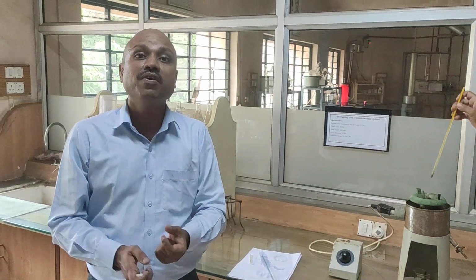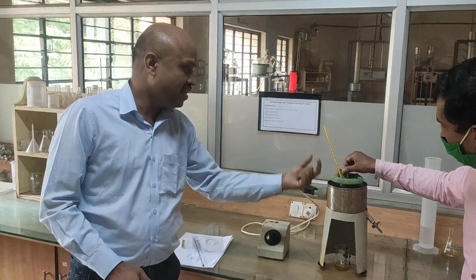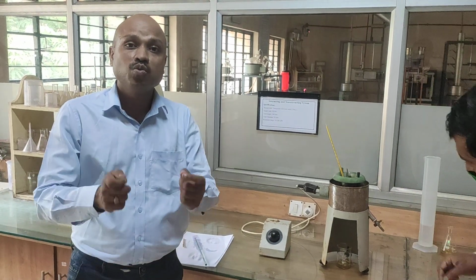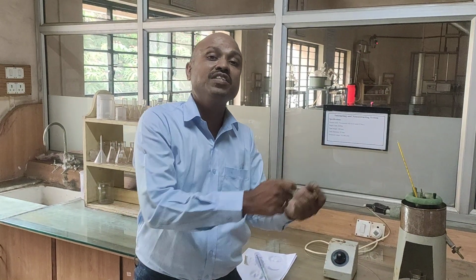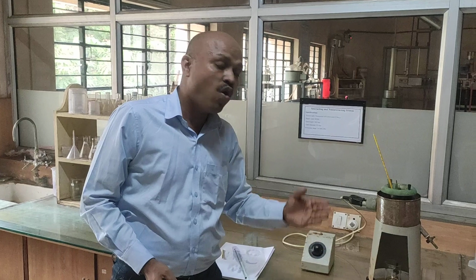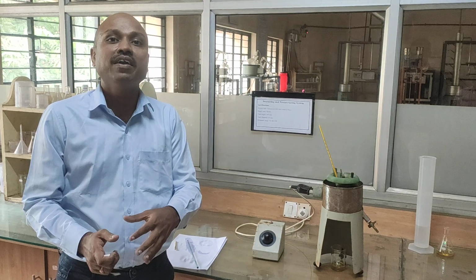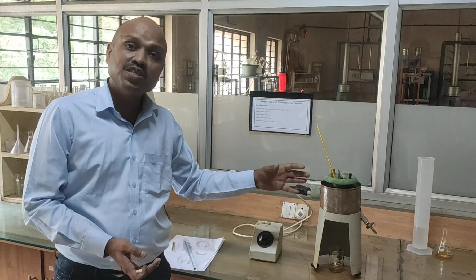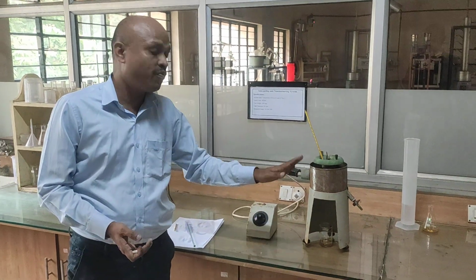Viscosity in liquids is governed by cohesive force of attraction. So when temperature increases, the distance between the molecules increases, the cohesive force of attraction decreases and hence viscosity decreases. As far as the time pattern is concerned, with increase in temperature, as viscosity is decreasing, the time required to collect the same amount of oil should be less in comparison with the lower temperature. As we go on increasing the temperature, the viscosity of the oil will go on decreasing and hence the time required for the collection of the same amount of oil will go on decreasing. This is what we are supposed to prove by performing this practical.